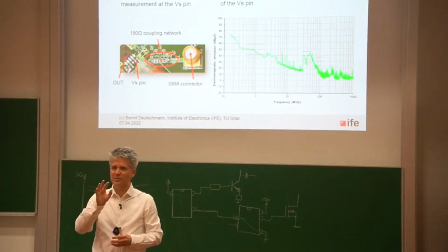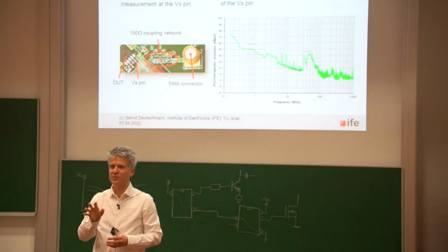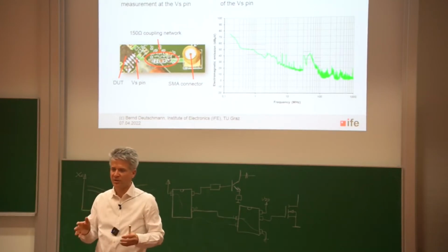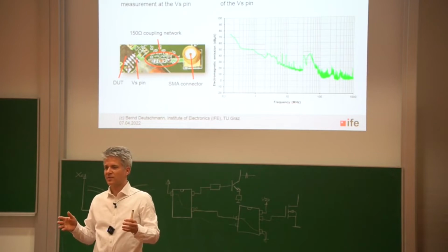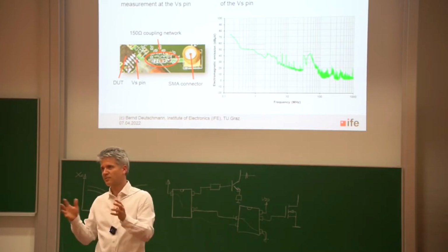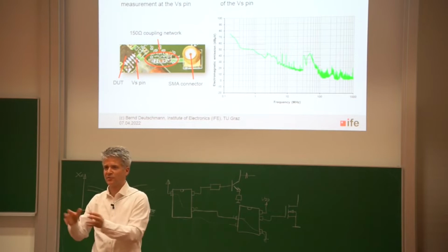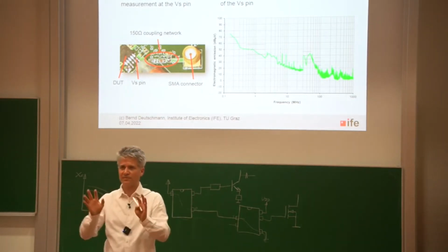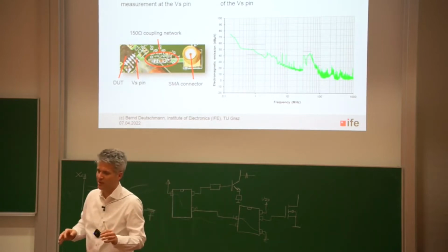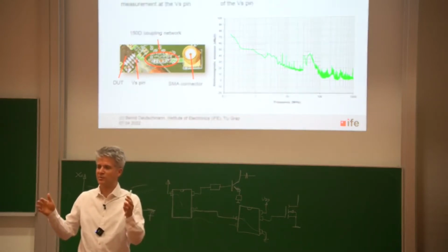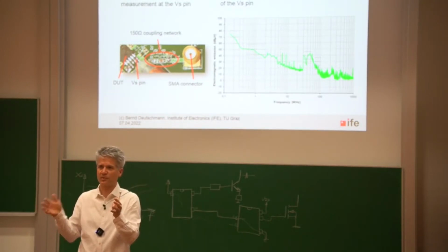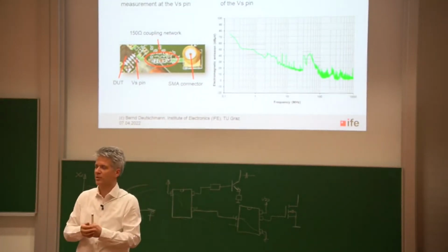Okay, yeah, it comes very close, but it's not really the frequency span. Frequency span is usually... I have to explain a little bit more what's the difference between an EMI receiver and a spectrum analyzer. Basically, they are the same. The frequency span is usually the frequency range between the starting frequency and the stop frequency.